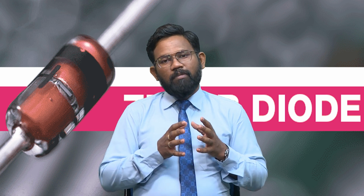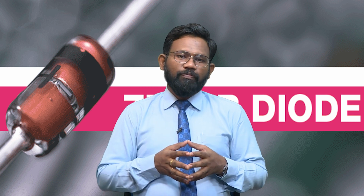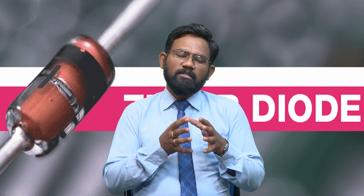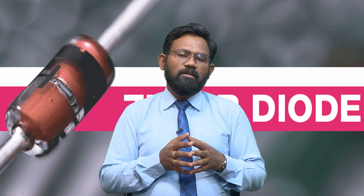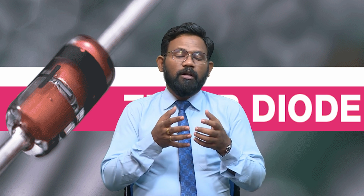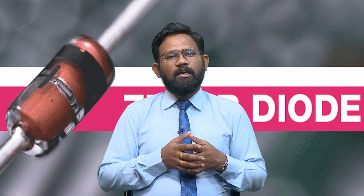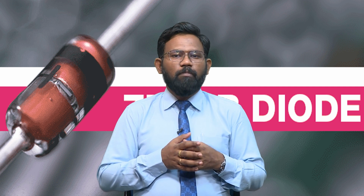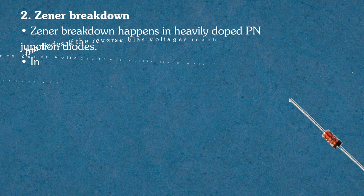junction diode. But the Zener diode is designed and manufactured in such a way that this reverse direction current will not damage the diode, but will instead become the working region for the Zener diode. That is why the Zener diode is a specific diode that is made to operate in this reverse voltage area. Now what is Zener breakdown?